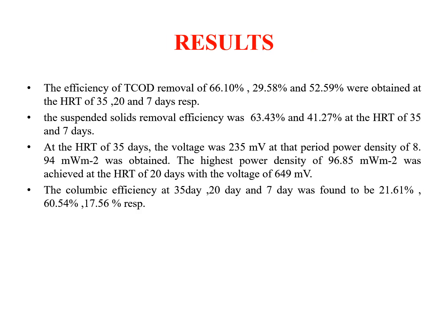Results: the efficiency of the total chemical oxygen demand removal of 66.10%, 29.58%, and 52.59% were obtained at the hydraulic retention time of 35 days, 20 days, and 7 days respectively. The suspended solid removal efficiency was 63.43% and 41.27% at the hydraulic retention time of 35 days and 7 days respectively.